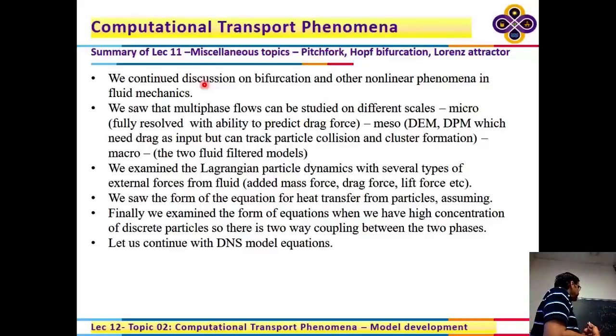What I expected, and I still expect, and I need to understand that, is that if you give constant pressure here, this equation won't be satisfied. It's COMSOL's responsibility to satisfy both these equations, right? Because it found this correct velocity field, and that velocity field doesn't depend on the pressure field. That makes sense, because this velocity field is driven by a moving boundary, right? So that is correct, and when you feed it into this, it will not satisfy the second momentum equation. And COMSOL should then correct the pressure in such a way that it is satisfied, and it's not doing that, you're saying. I will explore and see whether I can understand.